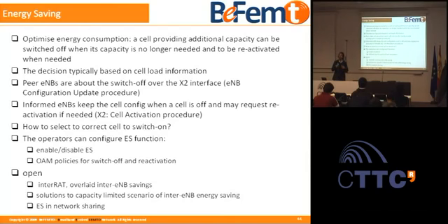And the only meaningful way of minimizing your energy is switching off your base station. Now, if you switch off your base station, you can't serve the user, so you have a problem here. But if you design it well, if you know that in the evenings there are times when your capacity demands are very low, and you are able to hand off everybody who's in your cell to your neighboring cells, you just go to sleep.